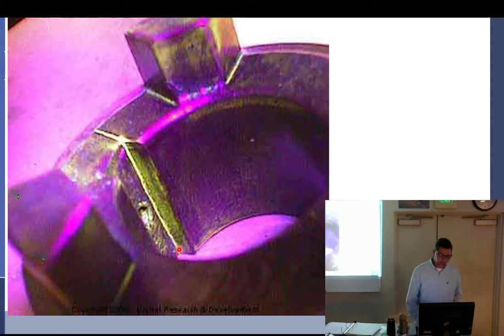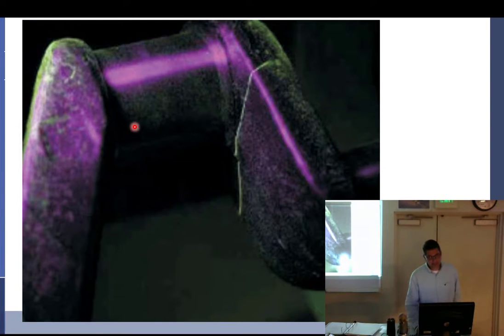So here's a keyway. I've got this right here in this keyway. Is that a crack or not? You'd say probably not. Then I look right here, and if that's going this way, oh yeah, that's really cracked. So look at how that crack comes around the keyway. Even in the lower part, in the hollow section, it looks curvy too. It's not straight, like you can see in the radius bins, that's more of a straight line, but if you look down you can see it turning, spidering, like it's cracking. Yeah, I think so. All right. That is a busted crankshaft. It looks like it. It's a crack.